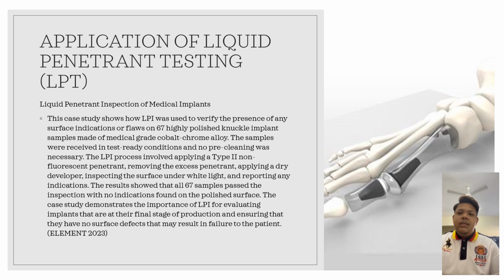The samples were received in test-ready condition and no pre-cleaning was necessary. The process involved applying a type 2 non-fluorescent penetrant, removing the excess penetrant, applying a dry developer, inspecting the surface under white light and reporting any indications.